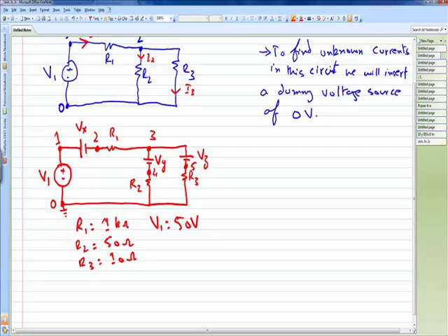Now when we use this to define the circuit in the code, we have to start from the very first line. The very first line is a blank line. You cannot write code on the very first line. So the first line is just the title, so we can say this is a test circuit here, and now we have to define the elements. It's up to you, there is no sequence required to write the code. I mean, you can write R3 at the very first line and you can define V1 at the last line, but it does not matter.